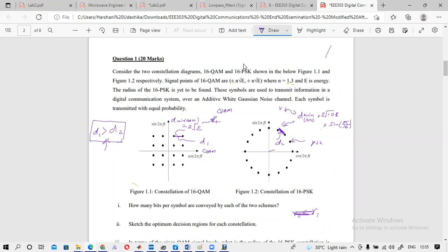If you have a tower like this, let's say this is a 4G LTE site. Practically, if we get around 32 dBm with an SNR of 22 dB, it is a very good value.